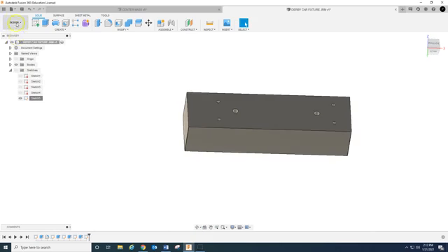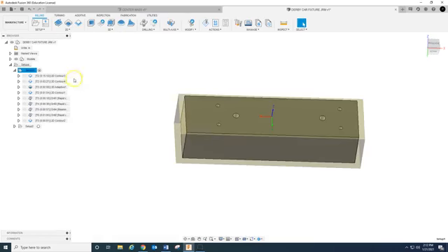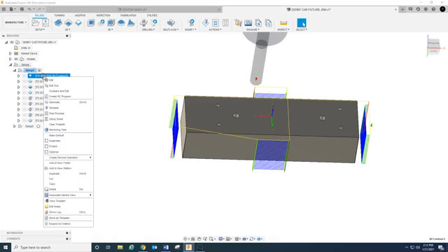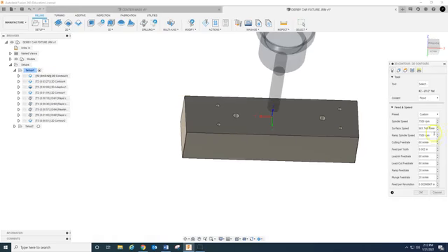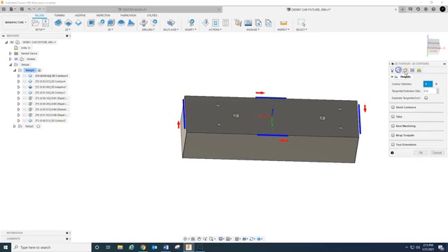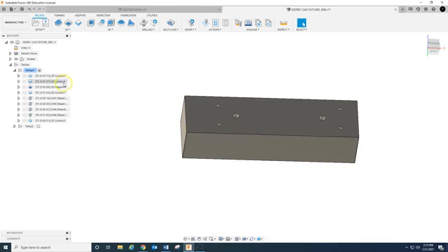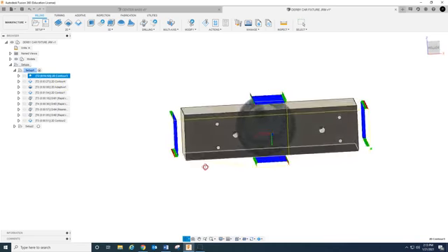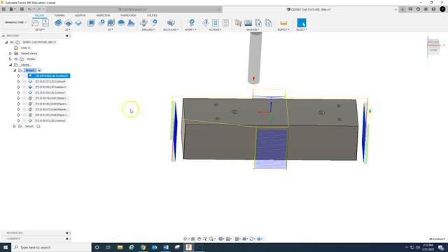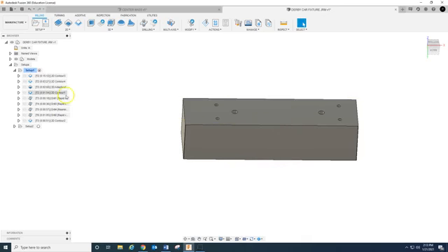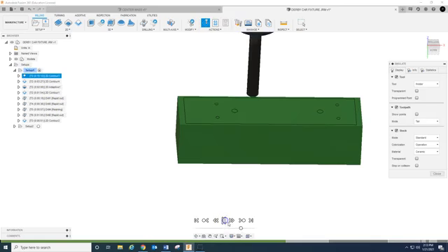All right, so I needed a way to communicate op1 to op2, and that is just an easy way of doing that. I can't believe I've got that running for 15 minutes, but yeah, I did pretty slow feed rates and all that, and I only went down like 50 thousandths per pass, so it's eating up a lot of time. So that was just the way we communicate that. So there's where we're roughing it, there's where we're finishing those, and then we're going through doing the rest of it. So let's simulate this.